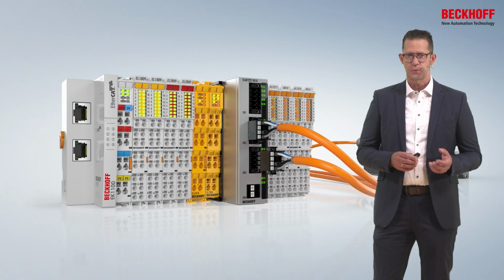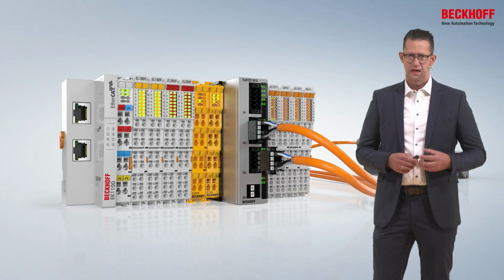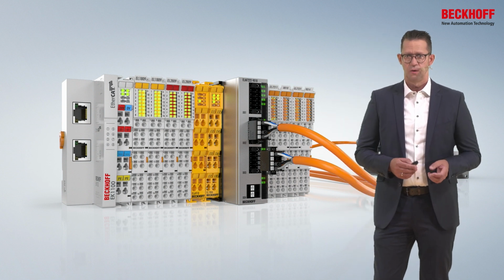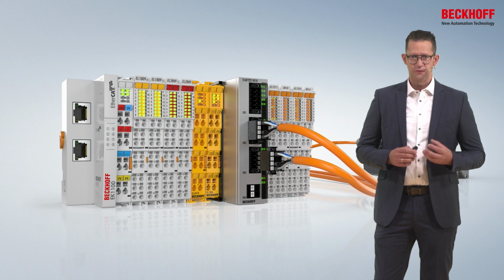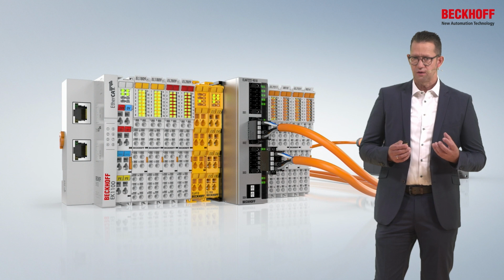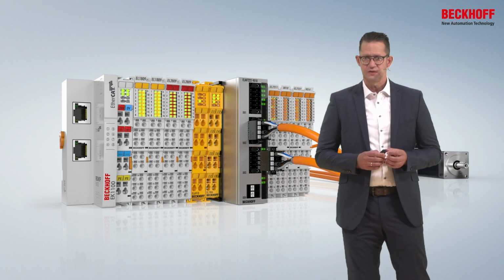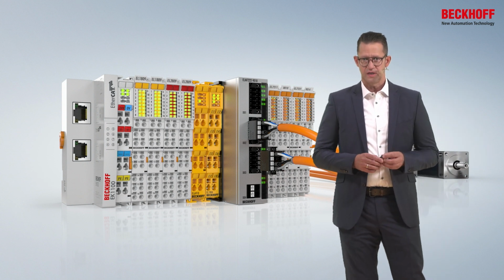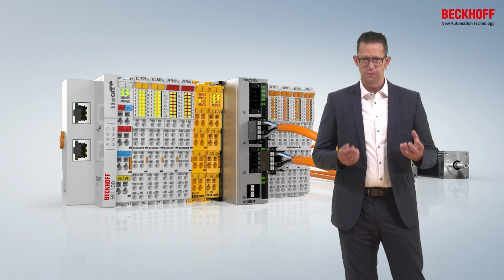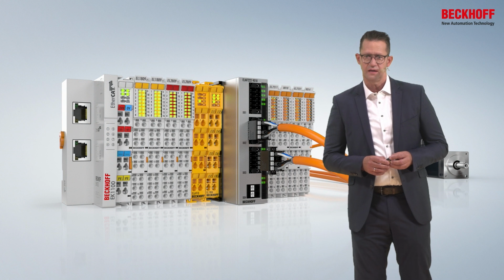On the one hand, operating with the TwinCAT NC. In this case, the NC generates the set points, either speed or position set points. If the terminal is operated in CSP mode, the control loop for the speed controller is then closed in the drive. That means directly in the terminal. The connected feedback is then used for this function. Of course, this means that the selection of the feedback, which means the resolution, has a significant effect on